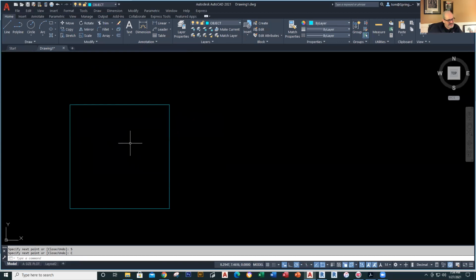All right. So now the next thing I want to show you as you go through that, there's a couple tools over here on the far right that actually go hand in hand. You've got Object Snap, which is right here. That's what allows you to draw a point in AutoCAD from a geographic feature, such as an endpoint or a midpoint or a center, if it's a circle, and actually have it snap to it, which is mathematically precise to be the point that is described. So an endpoint would be actually the very end of the line.